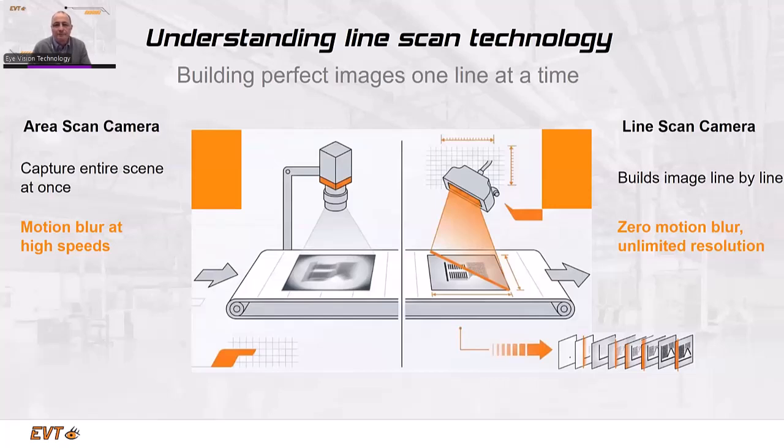And therefore, finally, the image quality is much better than on an area scan camera. You have all these side effects from the lenses, because if you have an area scan camera, you have to illuminate the complete area, and also you deal with the lens so that you have in the complete field of view a non-distorted image.